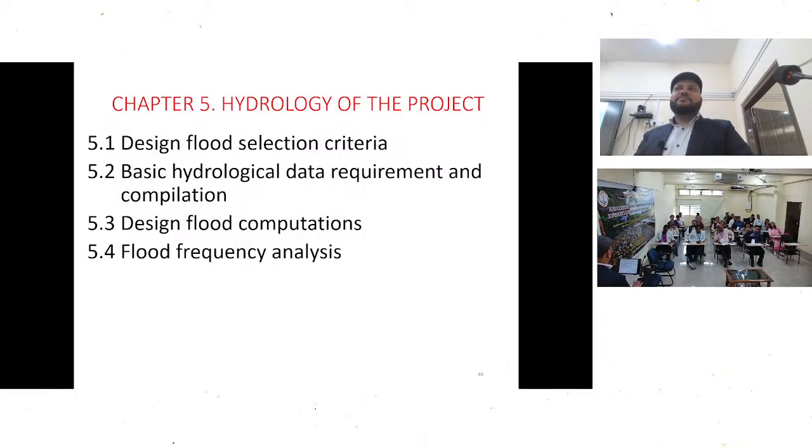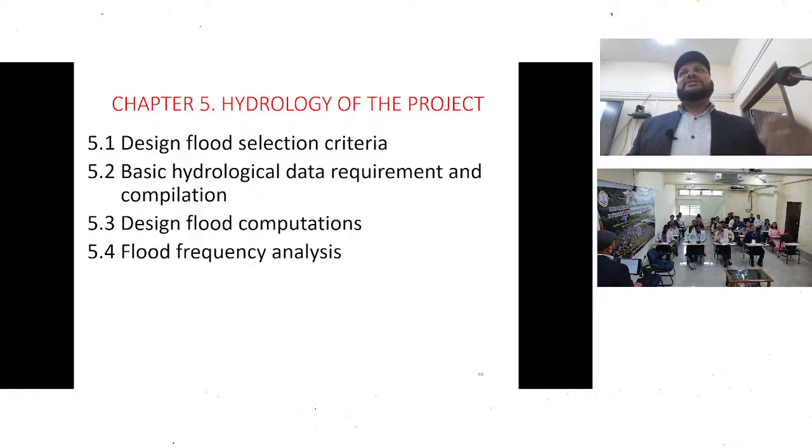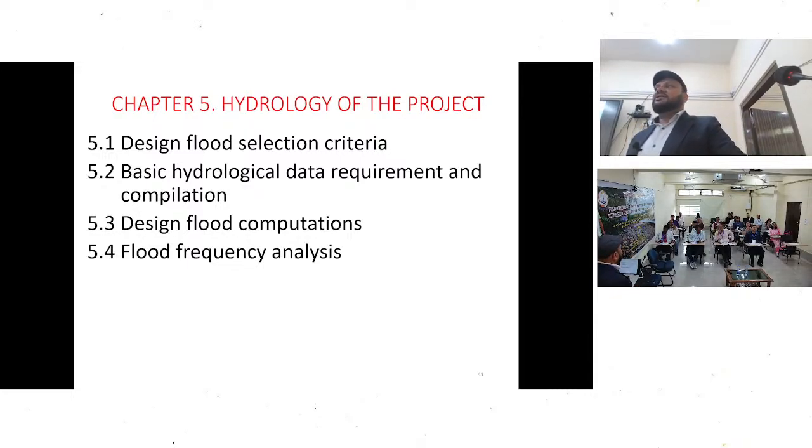Then the hydrology of the project. We should discuss hydrology design and flood selection criteria, because everything depends on the hydrology. How much HFL is there? Earlier Bansal sir was telling about flood frequency analysis. We do flood frequency analysis to set HFL, because we construct any project for either a 25-year flood return period, or a 50-year flood return period, or 100 years, depending upon the requirement and needs.